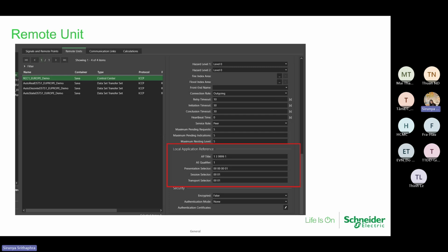It's TCP/IP, for IEC 104. So what about commands? Does it get commands from all of those? Yeah, probably not, right? Actually, this is a really difficult thing that we have to consider. But so far we have 10 connections and we can do the command for every control center. So for example, this RTU can receive those commands from all of the control centers. Yeah. Oh, okay.